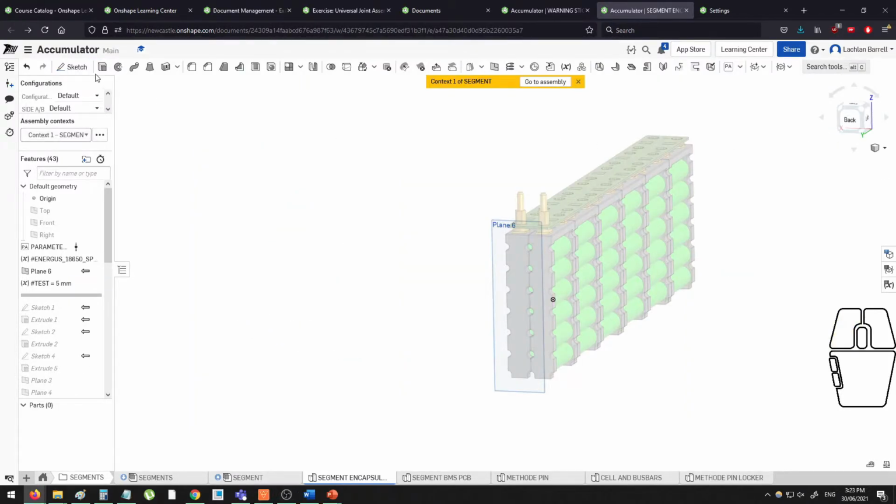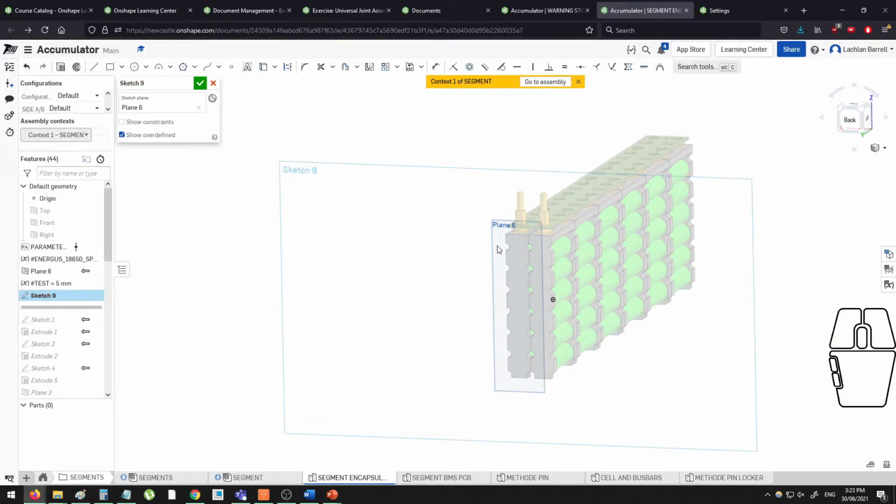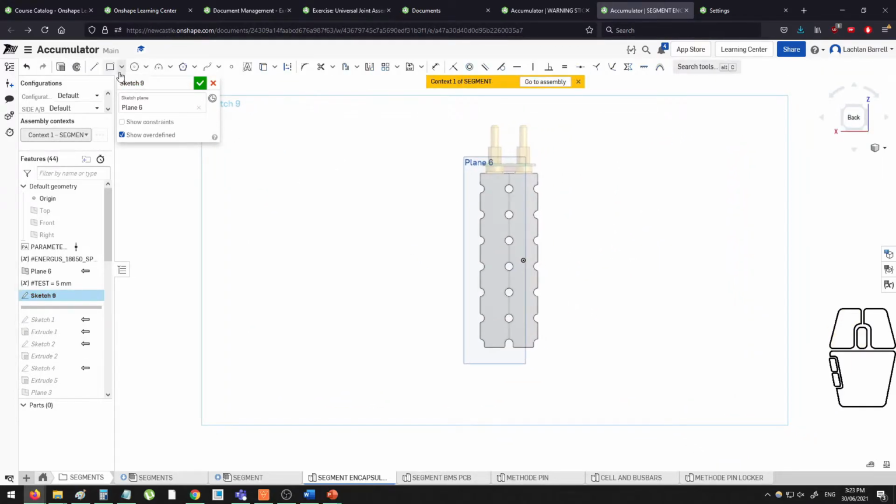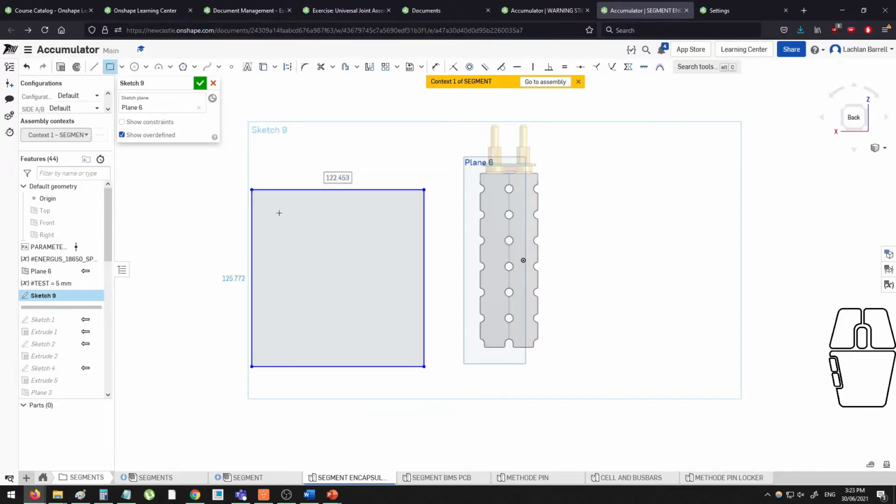Another drawing tip is if we go into a sketch here, you may have noticed that you can't actually set two dimension values to be the same. So if I try to dimension these ones here, in Creo, I would be able to grab an equal constraint and apply it to the actual numerical values here, which I can't do in Onshape, and honestly it's kind of illogical that you could in Creo. The obvious approach is to just make the line segments themselves equal. Obviously that's a bit over-dimensioned. Cool. So that's one approach for it.